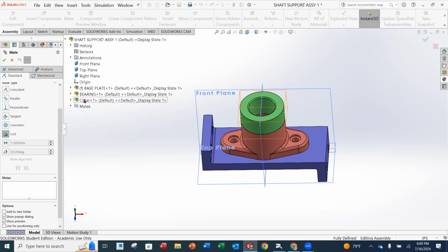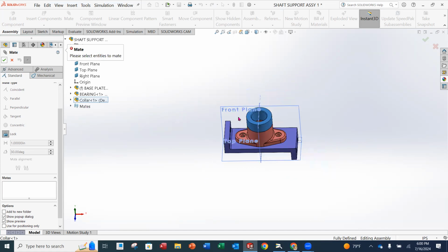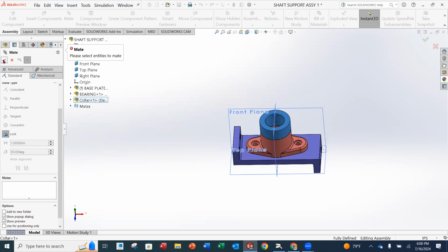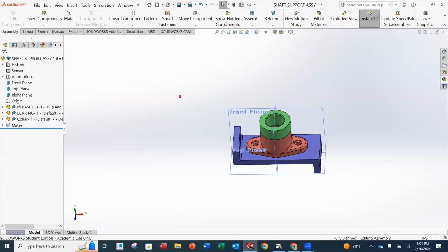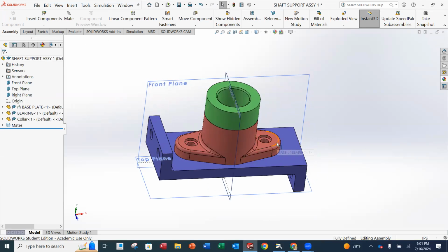That's another way to do it. So you would select the collar right here, select it, and then you can just hit lock. And then that way it'll be locked as well. Yeah, when you do the constraint, lock the rotation is an option. Yep. Thank you. There we go. Okay. Thank you. That's another way to do it as well, or align the planes like we saw earlier.